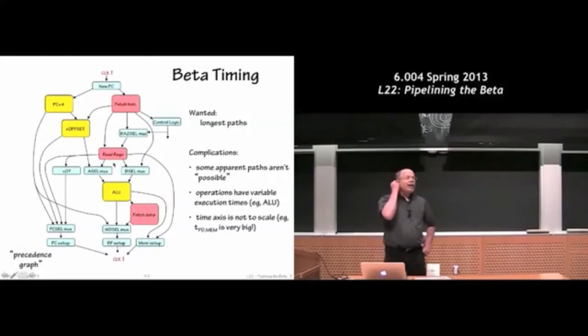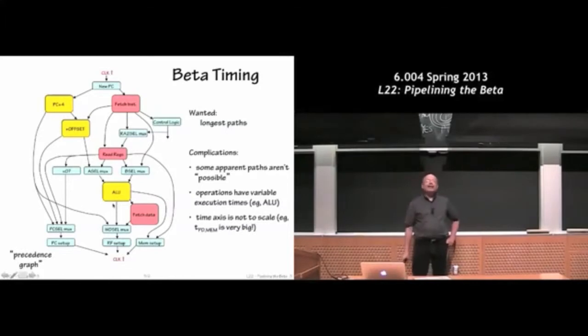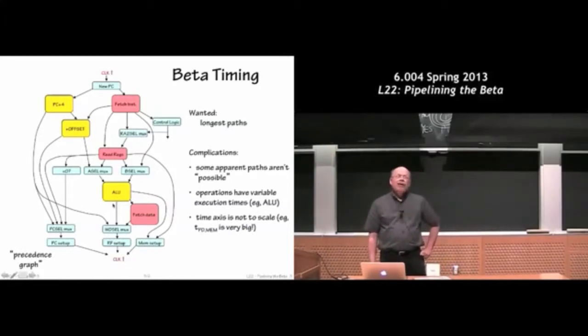The other blocks we want to think about are the big arithmetic blocks. So we actually have these big ripple carry adders, both to increment the PC, to perform the branch offset calculation, and to go off and actually do arithmetic on data that the programmer is trying to manipulate. And those ripple carry adders are slow, but nonetheless, in the timing diagram, we have to look at this and say, well, the ALU is in the way here.